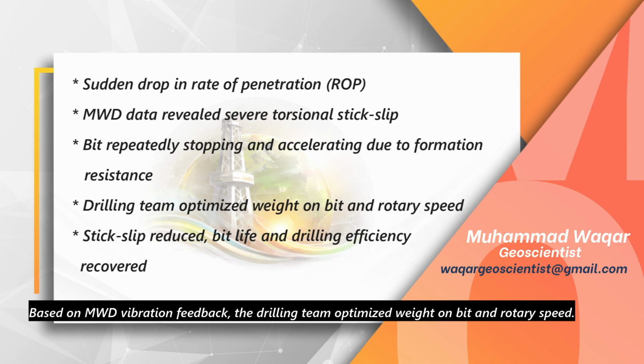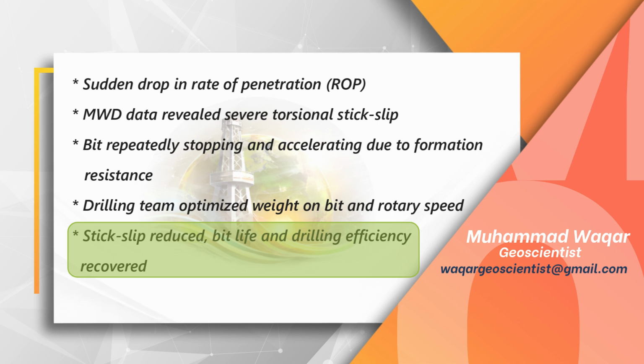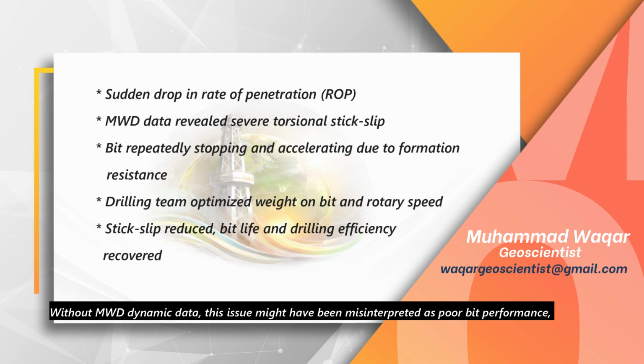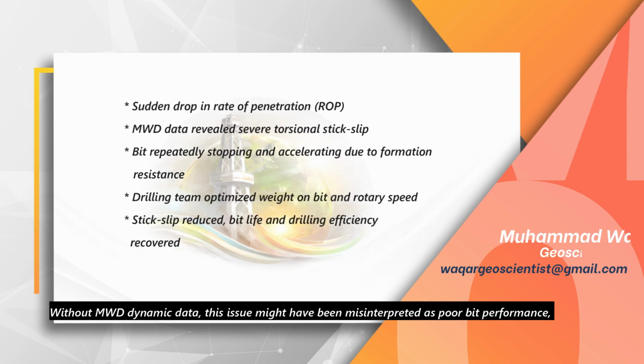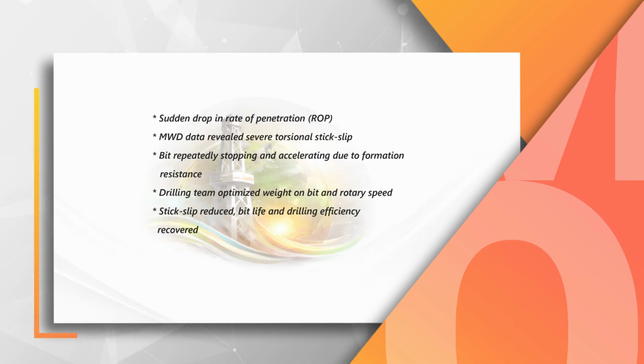Based on MWD vibration feedback, the drilling team optimized weight on bit and rotary speed. Stick slip intensity reduced, bit life improved, and drilling efficiency recovered. Without MWD dynamic data, this issue might have been misinterpreted as poor bit performance, leading to an unnecessary trip.